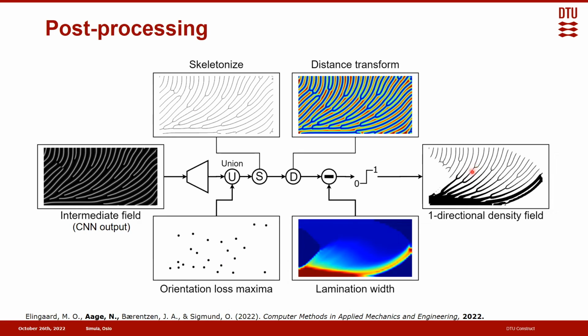Yeah, actually that's not it. The thing is the U-shaped splitters. That's what comes out of this post-processing tool. It should be a strict V. Again, it's back to the round holes. We do not want to see these roundings. Roundings are good for stresses, but if we want stiffness, we need straight sheets.